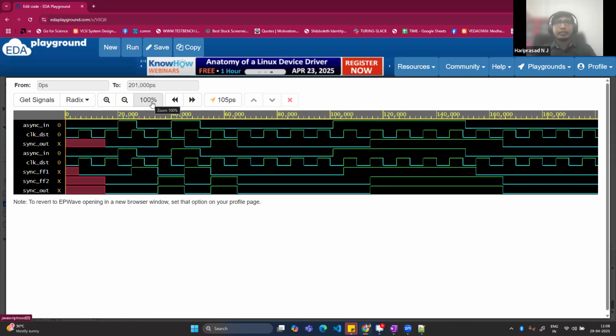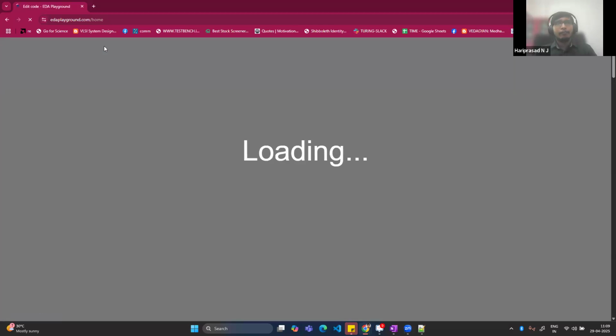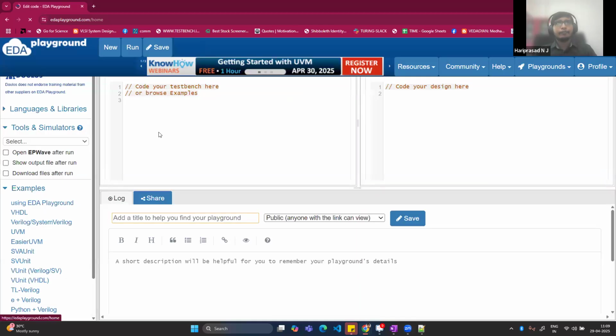Okay. So this is a two clock synchronizer, right? You have flip flop one, flip flop two, and you synchronize the asynchronous signal. Now we'll go for pulse stretching. Not pulse stretching, we'll go for the toggle synchronizer. Okay, pulse stretching is not popularly used.